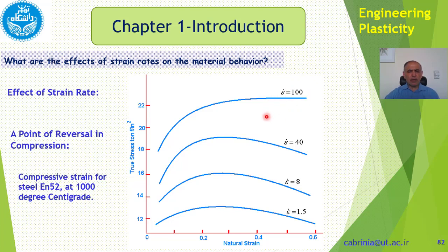The logic is when the speed of loading is so high that the heat transfer cannot compensate, because an increase in deformation, we said, causes an increase in temperature. But at lower strain rates, this increase in temperature can have its effect.